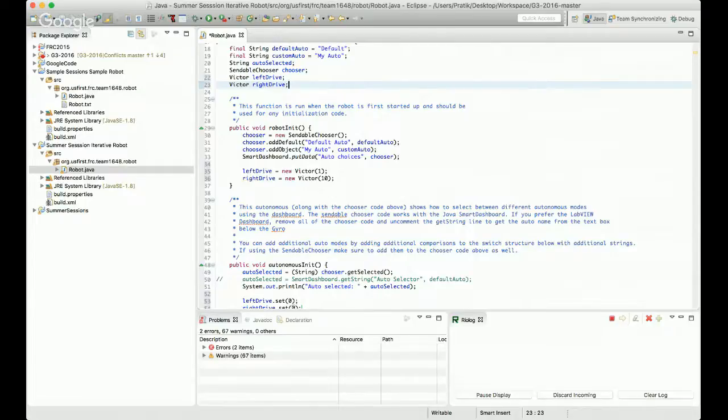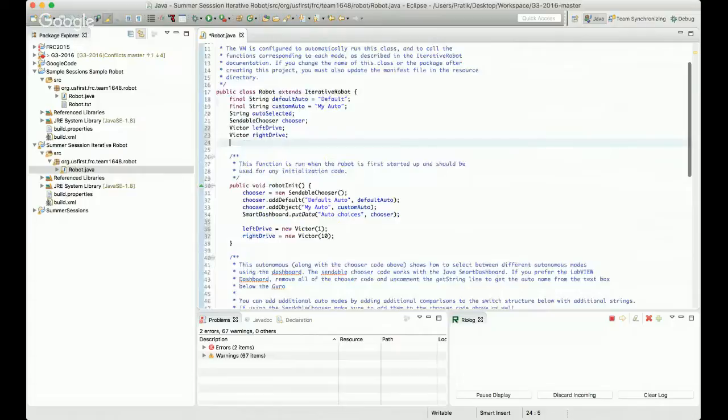And when we mount it horizontally on our robot platform, it tells us our heading from startup, and it gives us that in a PWM signal that is analog. So there is actually a gyro class in the WPI libs. So let's just call this my gyro. That's a bad name. Let's just call this robot heading, and we'll see if we can import that. Yep, it recognizes the WPI lib.